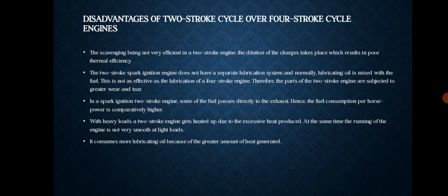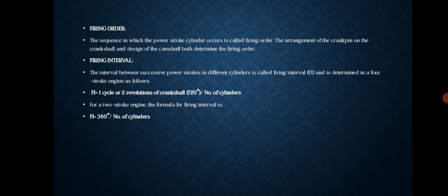Disadvantages of two-stroke cycle over four-stroke cycle engine. The scavenging being not very efficient in the two-stroke engine, the dilution of the charges takes place, which results in poor thermal efficiency.